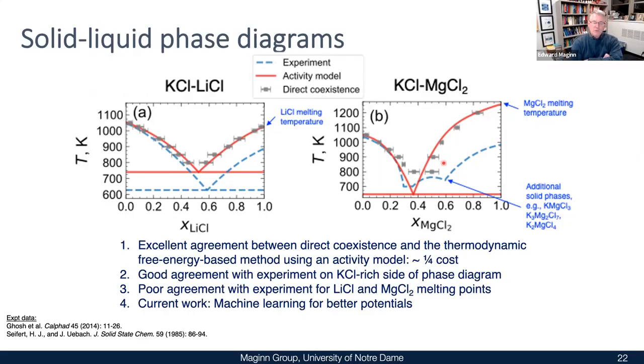off. What we're currently doing is trying to develop better potentials than this polarizable ion model. That model was fit to liquid phase quantum calculations. And what we're doing now is developing a machine learning potential using both the liquid and the solid phases. And we think we can get more accurate values and then apply these techniques to map out even more accurate phase diagrams. And then the value of that, of course, is we can look at salts for which we don't know the liquidus curve, because we can parameterize these models using ab initio methods.